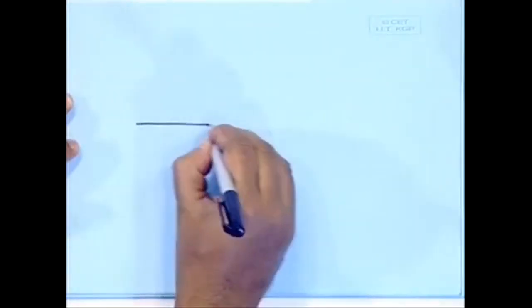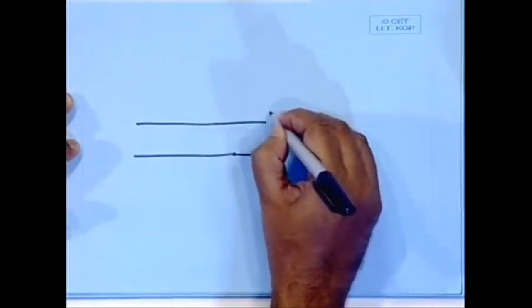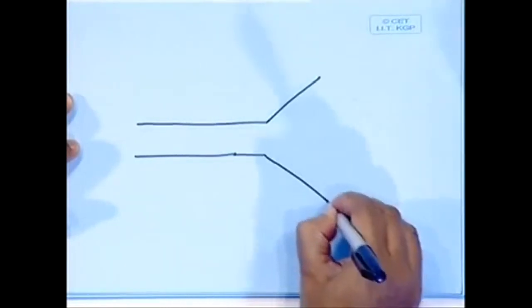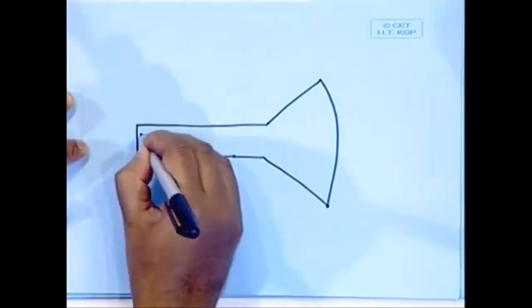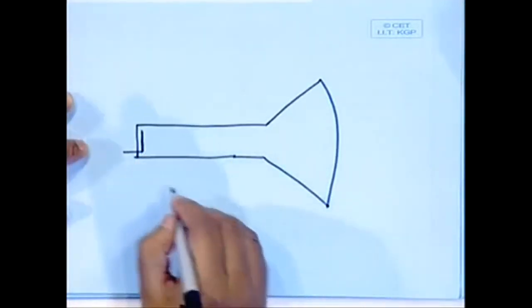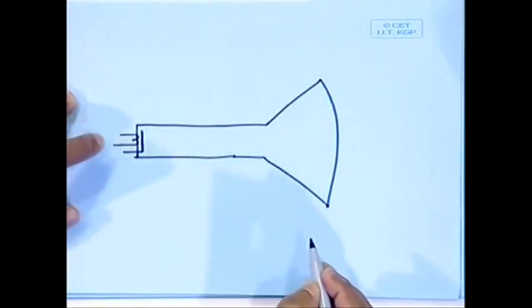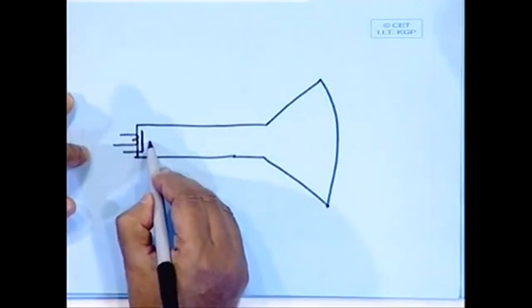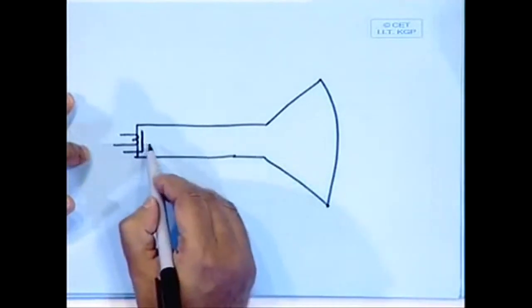as to what is there inside, and then you will be able to appreciate the controls of the oscilloscope in a better way. Here I will tell you what is inside an oscilloscope. Essentially, an oscilloscope has a CRT. So, this is the CRT, and here there will be a cathode, and there will be some heaters, and this will emit electrons.